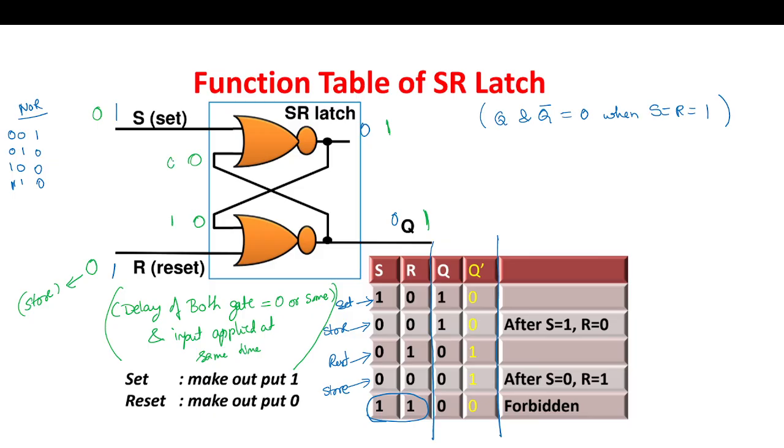This one comes here. So it's again 0, 1, which is 0, 0. Now it maintains at the state, the output will be maintained at 0, 0 because 0, 0 if we give. Now it is again changing. So in this way, we cannot predict what is the output when we give a value for store. So it is in the unstable state.